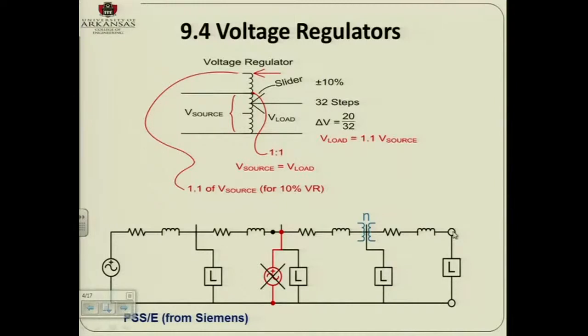What is the problem? Now what you have is real power and reactive power, and the problem is that the utility pays for Q. Your electric bill is in kilowatt hours, which means you pay for the peak power. But when the utility purchases power, they have to pay an extra charge, a surcharge, for the Q. So that's the reason why you have to use capacitors first.